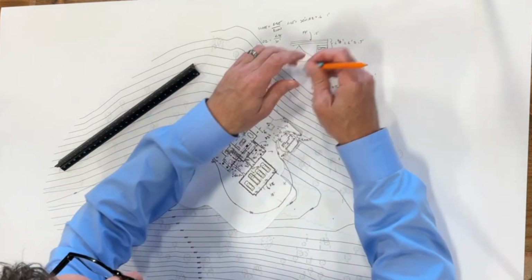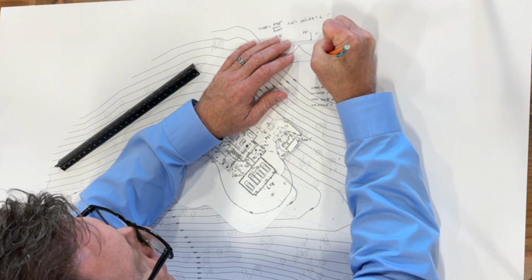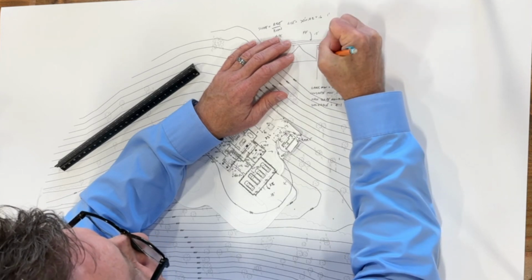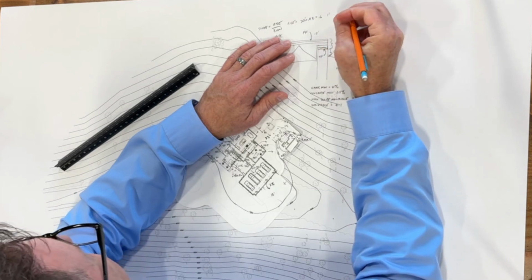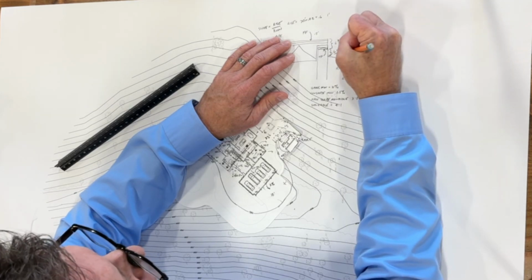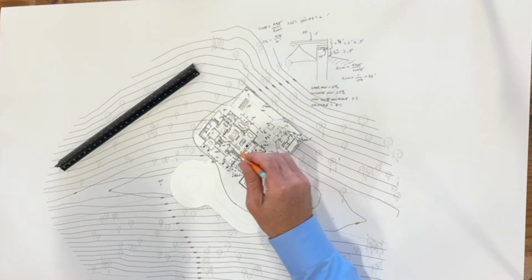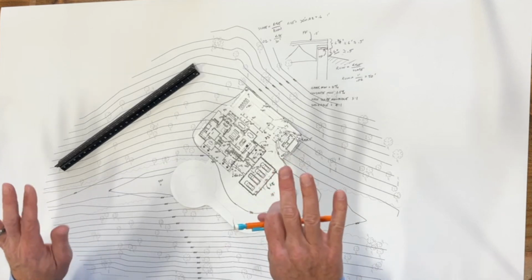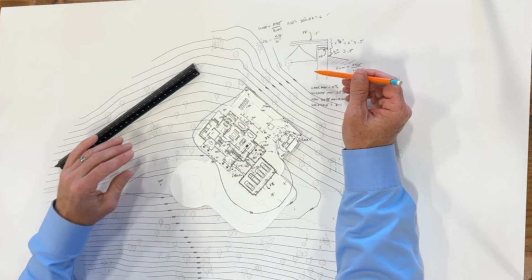And by the way, where this foundation is, I should show this a little better. This is an important concept here. Top of foundation is right here, and the ground will always be here, right? So the grade is always, we say 6 to 8 inches below, but I like to use 6 again because it just equals that 0.5 without getting too carried away on too many decimal points. But this is the ground, right? So the top of foundation here is at a 942, and we have 941 and 940. So where that line is, we're 2 feet below the top of the wall to just really make sure water never, ever, ever gets up over that wall, right?